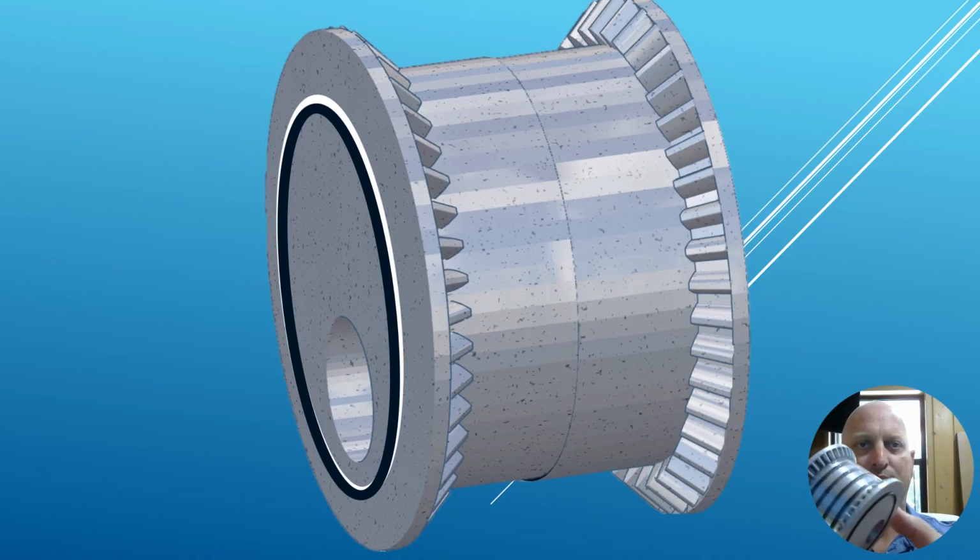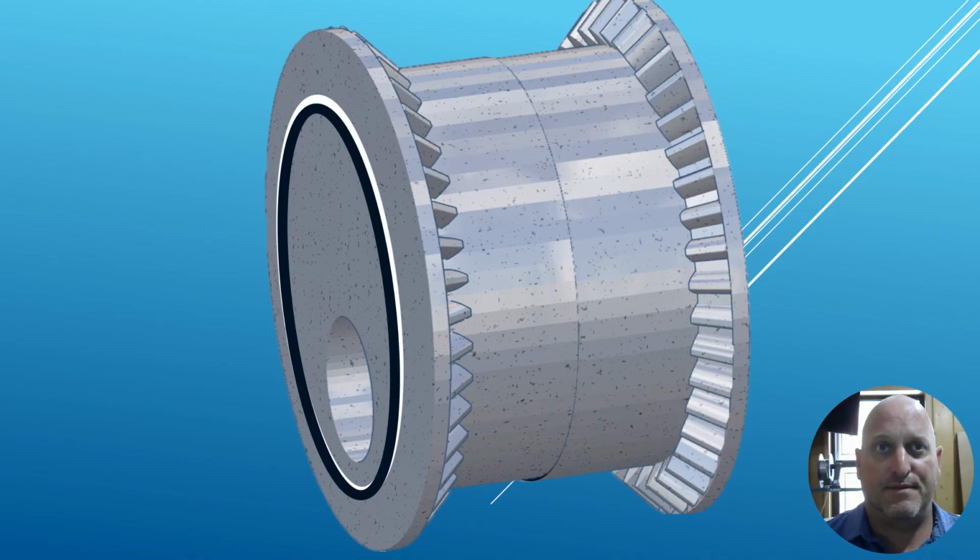I put a clear plastic case over this, so you can see that these standard O-rings are able to seal the fluid flow from getting into the interior workings of the valve and into those gears. But you also have an O-ring on the other side, and in this manner, we're able to perfectly seal the valve so that we have a wide aperture and a full close. And then these 4 O-rings or more, if you wanted to do a higher pressure application, are used to seal off the flow and shut it down.